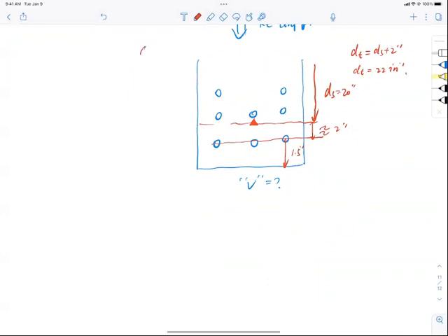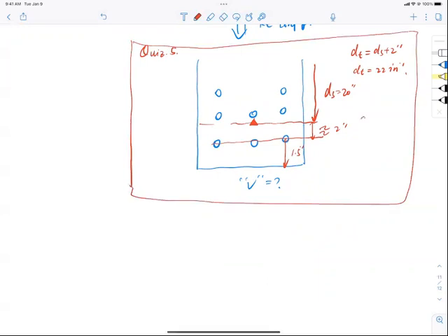Okay, so quiz number 5 is to check my configuration. Check detailing to see if this is going to work. Specifically, I just have 2 questions. For 5.1, the question is: is bw wide enough? That means, can bw of 11 inches accommodate these 3 bars or not? I just need a yes or no answer.